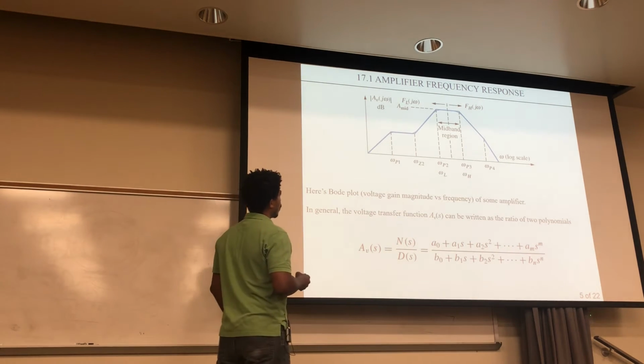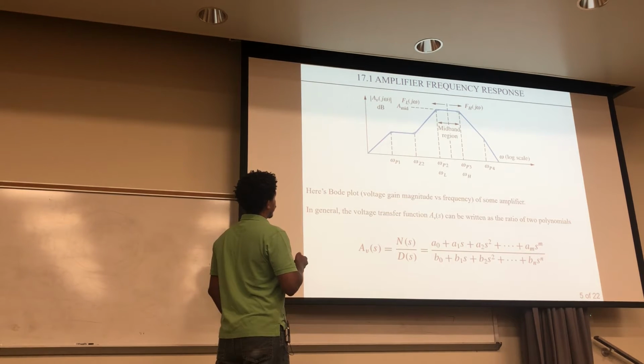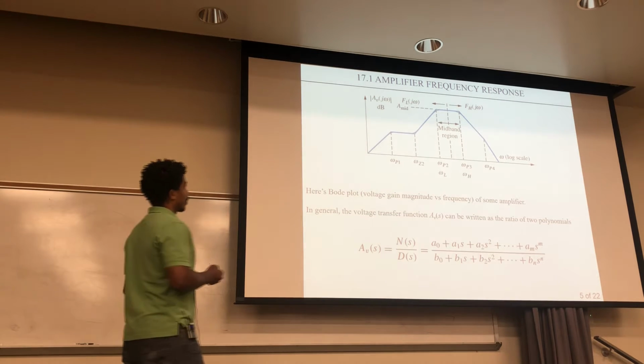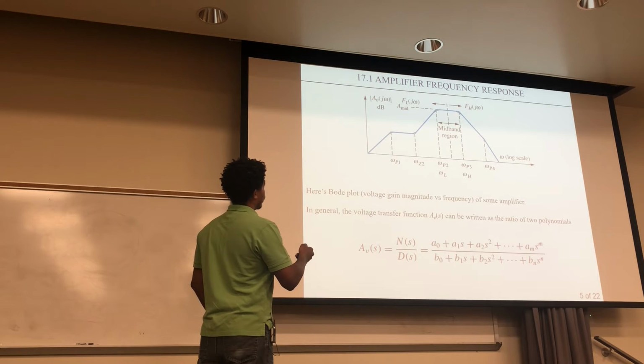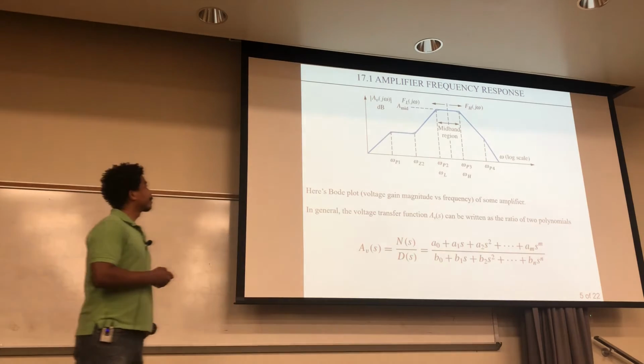From what we figured out previously, the poles bend your trajectory down by 20 decibels per decade for each order, and the zeros bend it up by 20 decibels per decade for each order. You see here where the poles are, bending down here, here, here, and right there. And the zeros bend up right there.